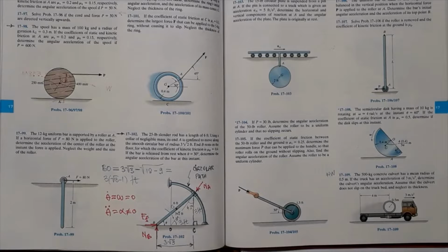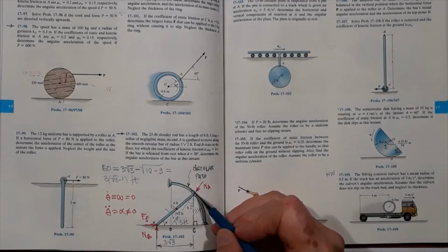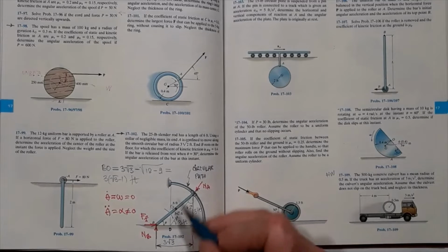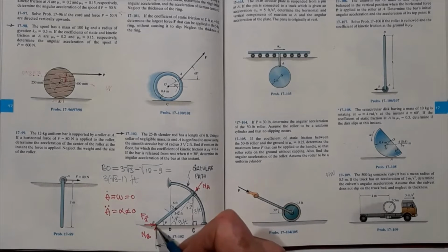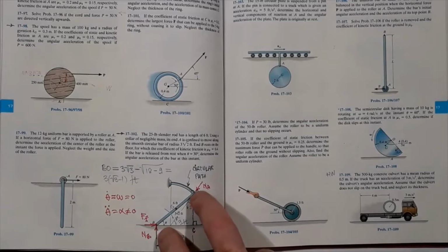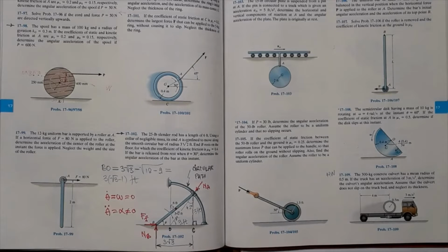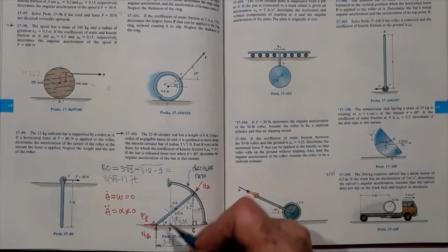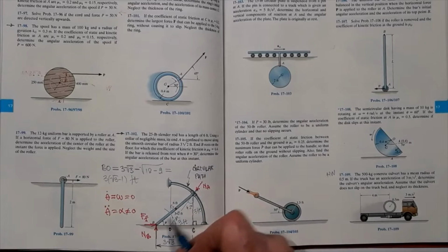this instance. Okay, I have already represented in red the normal force at A. That will be, since it's frictionless, has the direction of the center of the quarter circular guide. And then at B, we have the normal force, and then we have the friction force. There is an arrow indicating direction of motion, so friction opposes displacement at B. And this is about it. So, one more thing. We may or may not use it. Theta dot is going to be omega of the bar AB, and theta double dot is going to be alpha